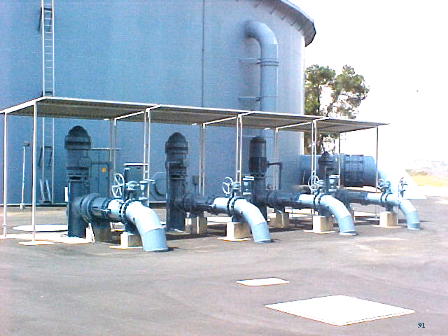If I had to guess, I'd say that it looks like they've got a VFD in here to provide that variable frequency, depending on the pressures or the demands downstream. You want to be able to just meet those lower ends, whereas you've got some heavy hitters here that will relocate this water into maybe another reservoir or pump out into the system in times of high demand.